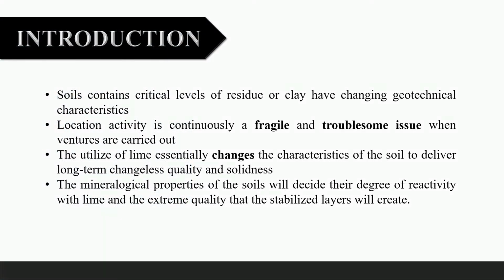Generally, improving on-site soil engineering properties is called soil stabilization. There are many ways to stabilize the soil, but our group chose lime stabilization as our topic. Soils containing a critical level of silt or clay have changing geotechnical characteristics, such as swelling and becoming plastic in the presence of water, shrinking when dry, and expanding when exposed to ice. Site activity is always a fragile and troublesome issue when projects are carried out on such soil.